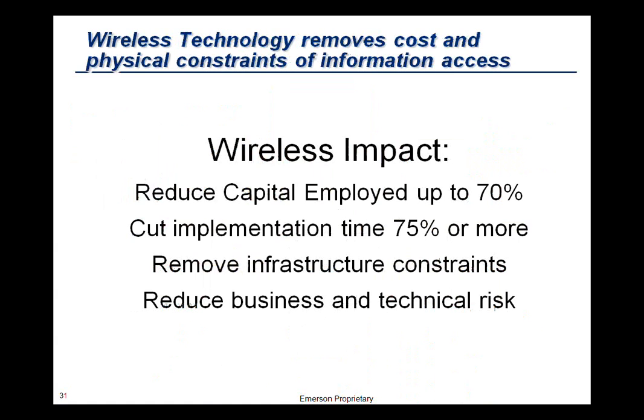This wireless can have a major impact, as we talked about before, in reducing the capital employed and cutting the implementation time here by more than 75%. As I mentioned before, being able to go out and take a device out into the field, install it onto a 2-inch pipe bracket, that's doing up 2 nuts fundamentally, and connecting the sensor, whether it be magnetic for a motor or a simple impulse line, dramatically reduces the time to get that measurement up and running. Not just from the cost point of view, but also meaning that that measurement's in play and able to be used to keep the plant running.